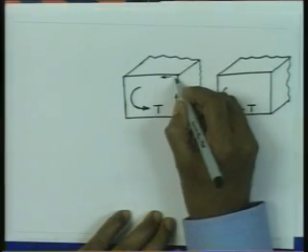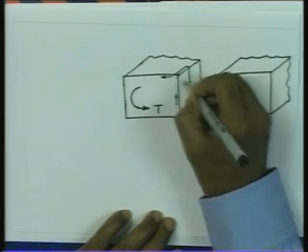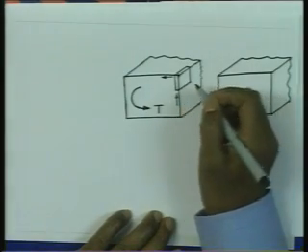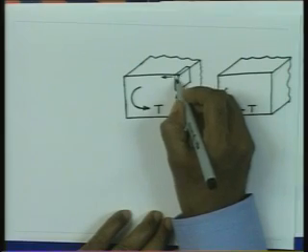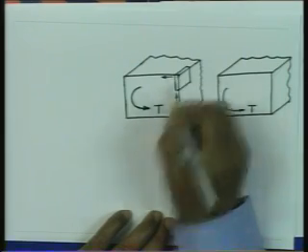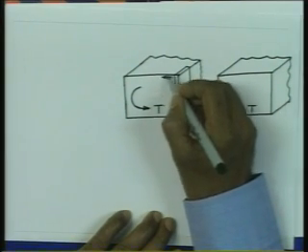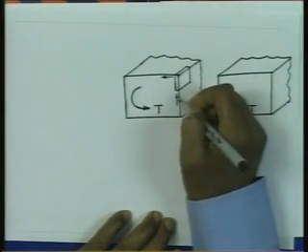We know for sure that if the stress is going to act perpendicular to this boundary, this stress which is acting, so just concentrate on this element that is located here, the stress acting on this area is going to be directed vertically upward, and that is again related to the slope of the phi surface in this direction, and since phi is 0 all along, the slope is 0, therefore this stress is 0.